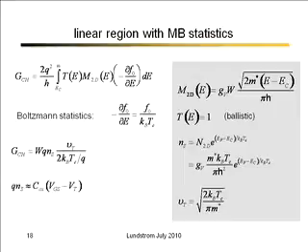Then we can bring in MOS electrostatics. I could do it in a better way, but I'm going to assume I'm above threshold, and we'll do it in a simple way. Above threshold, if we have a well-designed transistor, the charge in the channel is q times the number of electrons, which is gate capacitance times Vg minus Vt.